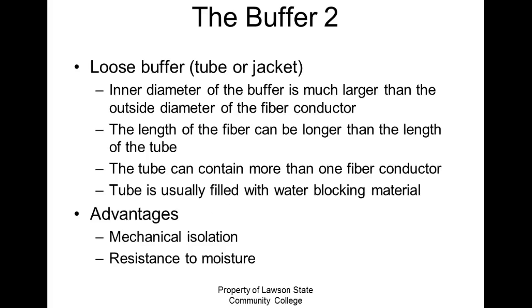Loose buffer. The inside diameter of the buffer is much larger than the outside diameter of the conductor. The length of the fiber can be longer than the length of the tube. The tube can contain more than one fiber conductor. The tube is usually filled with water blocking material, and this gives us what? Mechanical isolation and resistance to moisture. That makes sense? Are you okay?